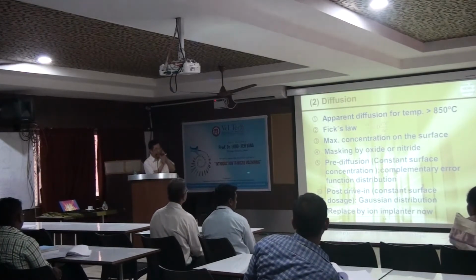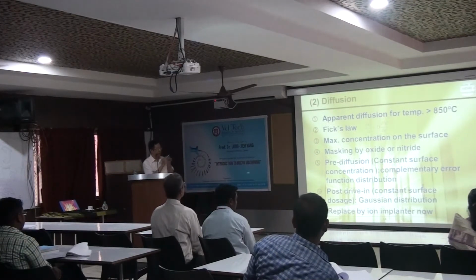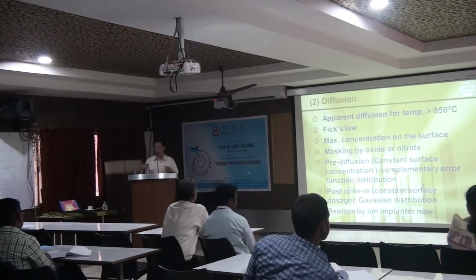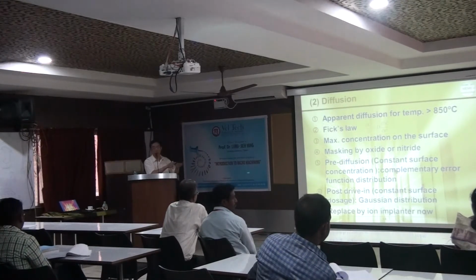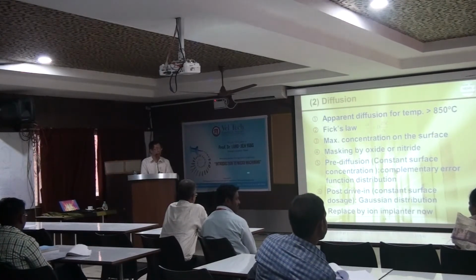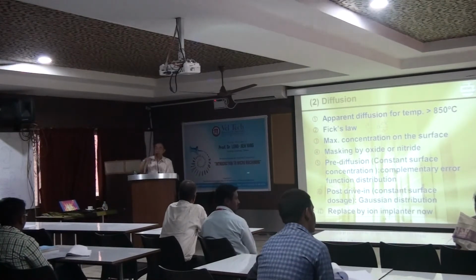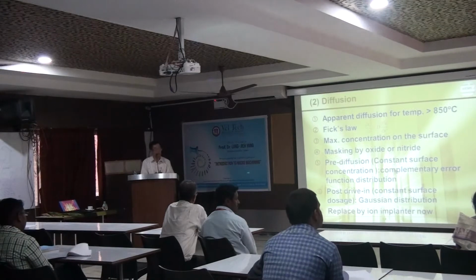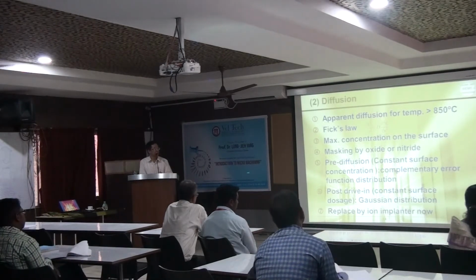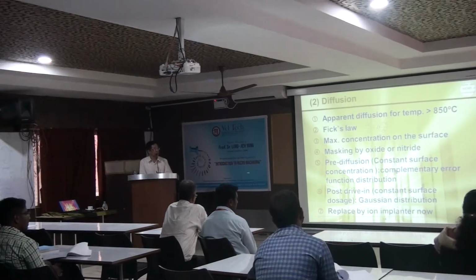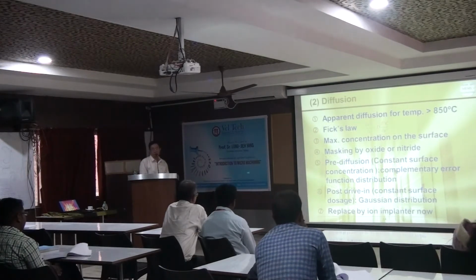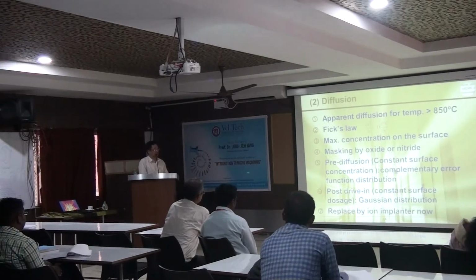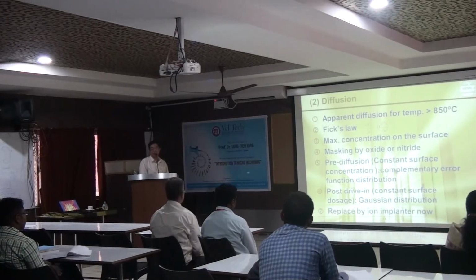But here, very similar, but a little bit different. We will not order them to do the anneal. We let them diffuse more into our wafer. So we call it the drive-in. Drive inside, drive more inside. What's drive-in? The mathematical model is about Gaussian distribution. It's a normal distribution, actually. Normal distribution.